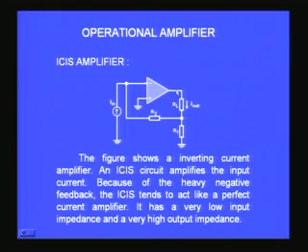You can see the current is sensed, the RL is in series with the feedback network. R2, R1 are the feedback part of the feedback network. So R1 gets the current which is part of the I out. So this voltage will have an influence through this resistor at the input. This is the feedback path that you have here, and this is a current source that I have connected at the input. So we should now find a relationship between the I output, the current output, and the I in,